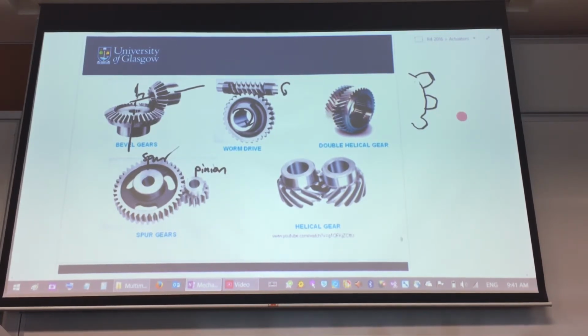What would it be, that point of contact? If you measure it, it will be just one line, because the other gear here will also be arc, straight, arc. So arcing and arcing, when they touch each other, is one line. But even that one line, under high speed, creates a lot of noise.